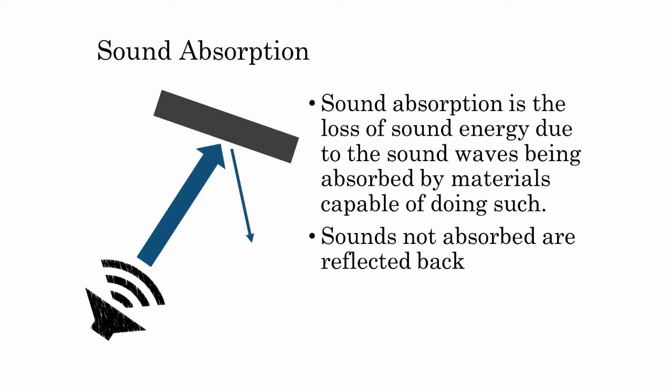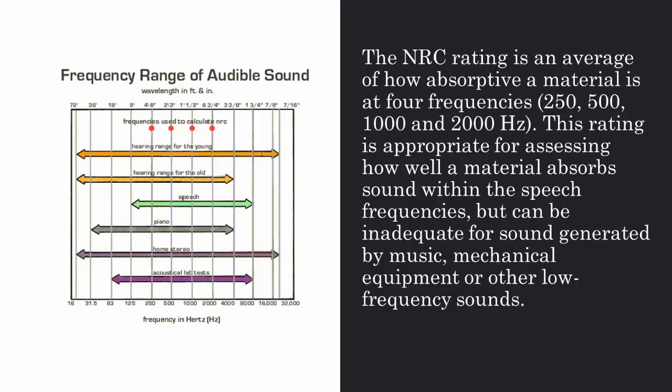Sound absorption. Sound absorption is the loss of sound energy due to the sound waves being absorbed by materials capable of doing such, while sounds which are not absorbed are reflected back. The NRC rating is an average of how absorptive a material is at 4 frequencies, such as 250, 500, 1000, and 2000 Hz.